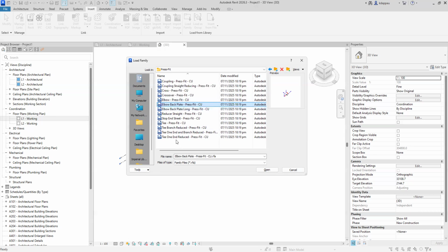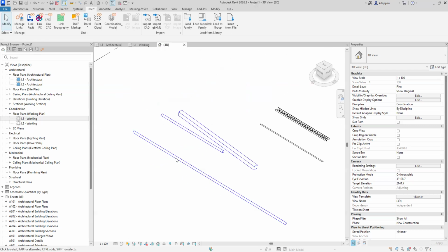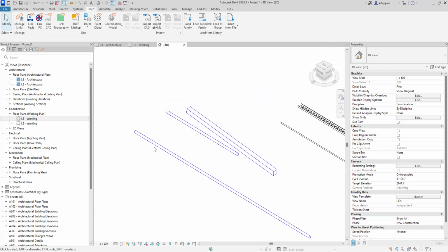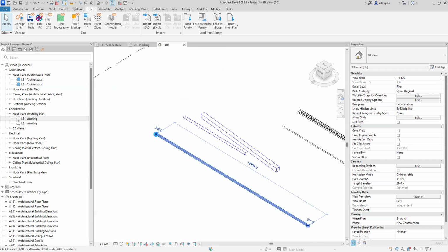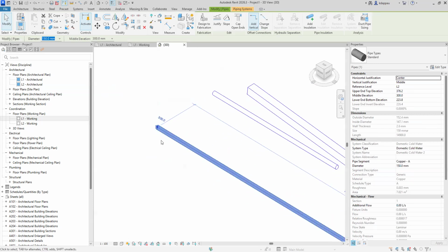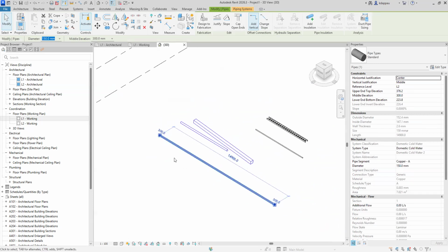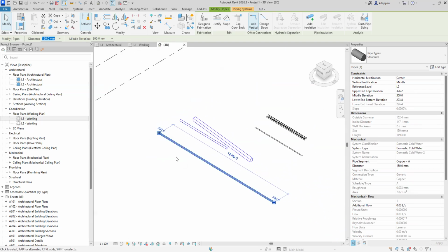Now, the point I am making is this one. Whichever pipe you want to work with and deal with, Revit only knows how to draw a pipe. But any pipe that you want to create, in terms of the type of pipe you want to create, is defined by the type of fittings that is applied to the pipe.